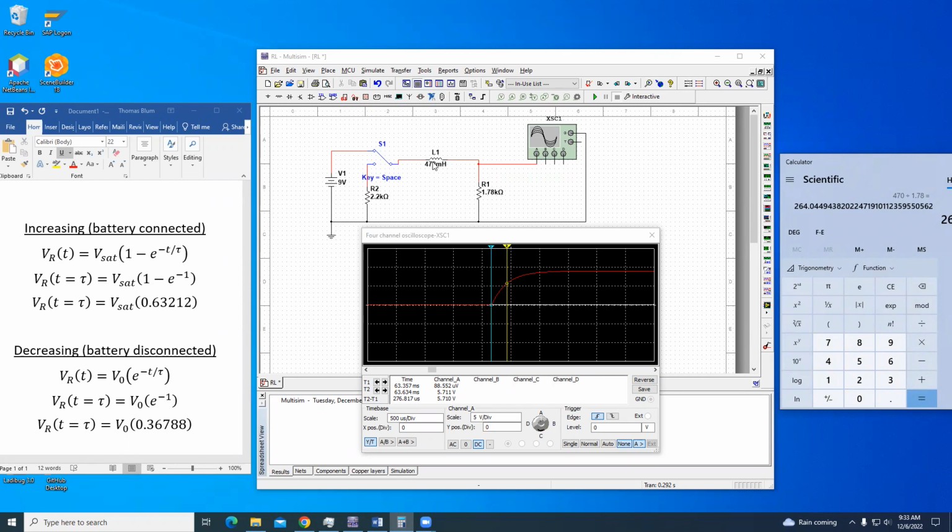Okay, and then the units. I'm dividing millihenries by kiloohms, and a henry divided by an ohm would be a second. And I've got milli, thousandths, divided by kilo, thousand. So I've got something small divided by something big. So I want something doubly small, if you will. So I'm getting microseconds, 10 to the minus 6. 10 to the minus 3 divided by 10 to the 3 is 10 to the minus 6, or a micro.